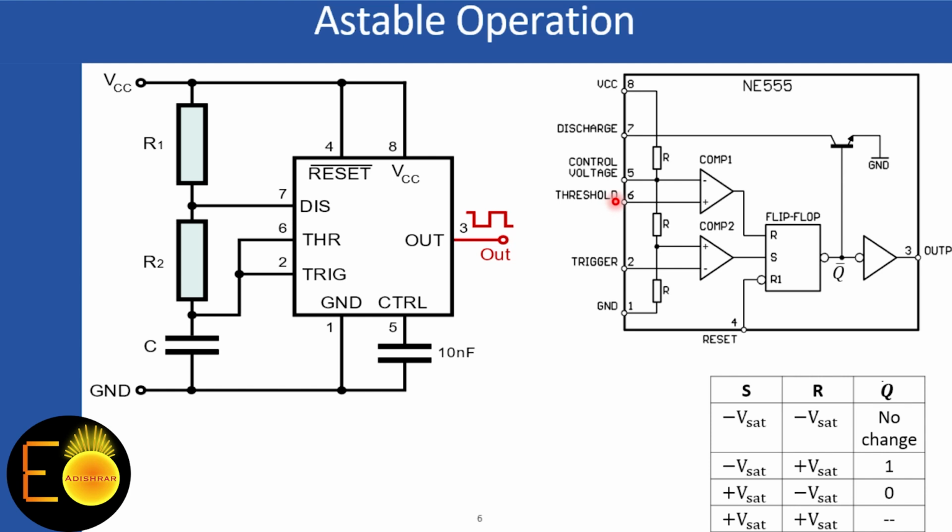So that's why the pulse width gets modulated, and in this way you can design a pulse width modulator, and this can also be treated as a voltage controlled oscillator, VCO. I will show you in LTspice that as the pulse widths change with respect to the applied voltage, that is the property of a voltage controlled oscillator, because the frequency changes with respect to the input voltage. So as the pulse width is changing, the frequency is also changing continuously.